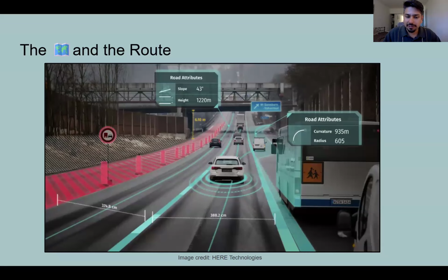So what I was saying first, I can give you 10 seconds to look at this slide. This is the lane-level information that we're talking about, and the routing operates in this lane world, where you want to find the optimal routes. What I was saying is taking the exit versus not taking an exit. In this case, it is clearly shown that we want to take the exit, but there are some other factors to take into account, like you might have an alternative route exit after this. All of these things can be turned into a multi-objective optimization problem.